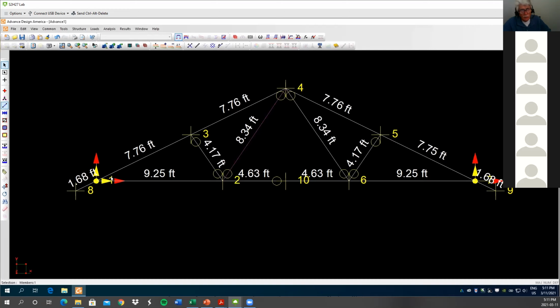So you got to pin it here. Let me annotate, so this way everybody can see it. You have to pin it here, but you don't have to pin it there. As long as it's pinned on three sides, the other side doesn't have to be pinned. You have to pin it here and there, because this member is continuous, but here you can't connect them all as being fixed, so they have to be pinned to each other. This is pin, pin, pin, pin. This is pin here, continuous there, pin there. So you have to pin there, there, and there. That's what's left to do. You understand?